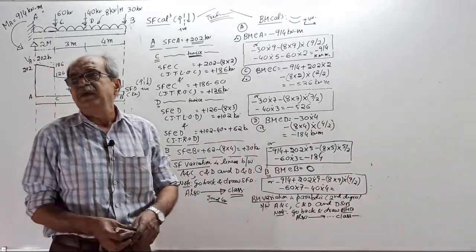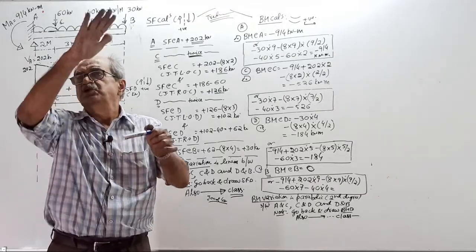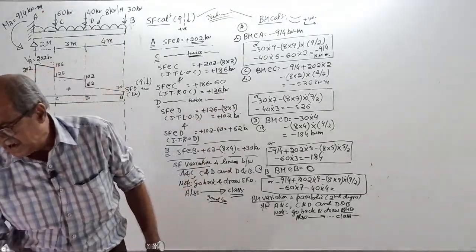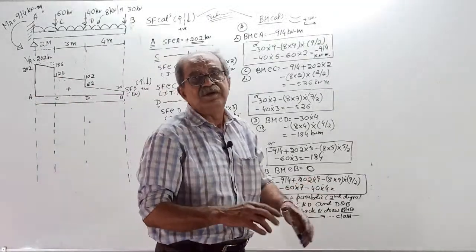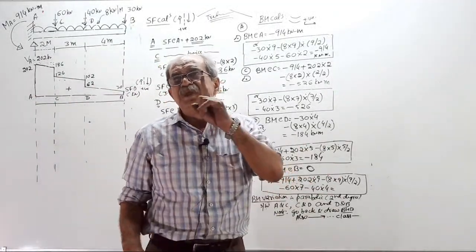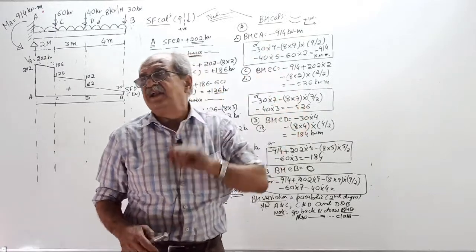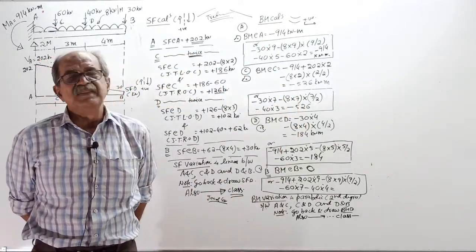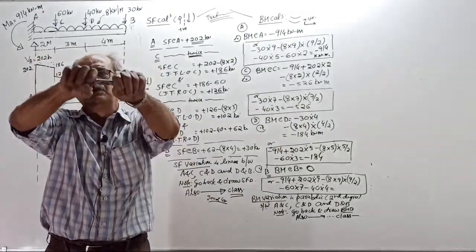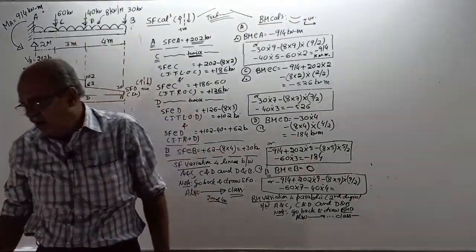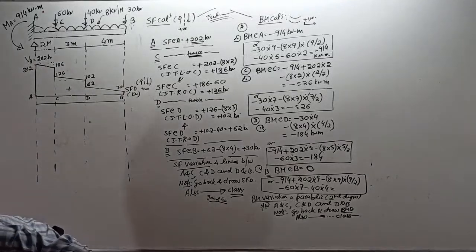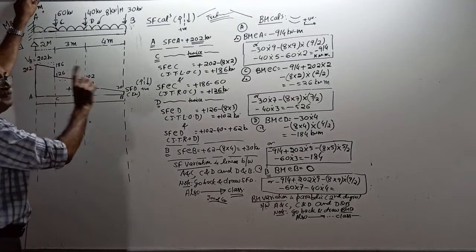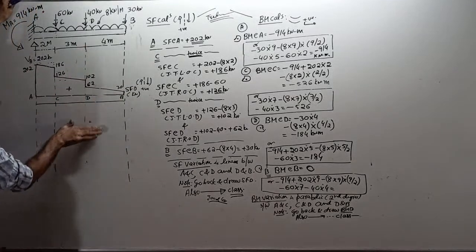And for a cantilever beam, when you apply only usual loading, whether it is fixed at left end or right end, under normal load case, will BM come sagging or hogging? Hogging. So negative, therefore you do not require any space on the upper side. I can use the full space.